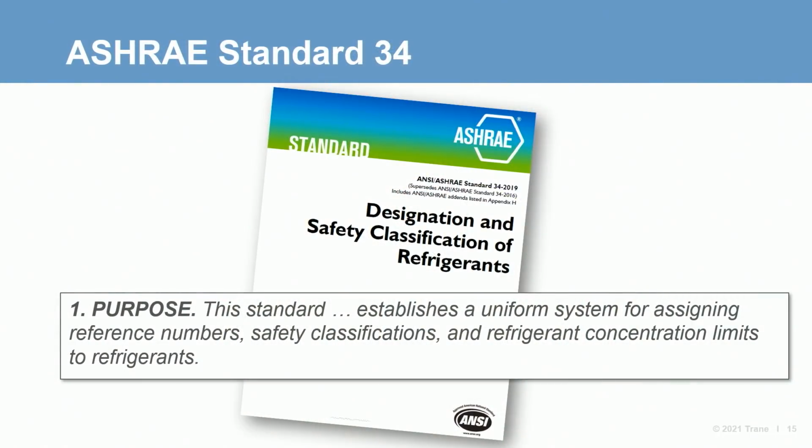First, it establishes a system for assigning reference numbers to refrigerants such as R410A. This helps avoid confusion caused by using brand names such as Freon, or complications of using the full chemical name or formula. Its second purpose is then to define the safety classifications and the refrigerant concentration limits for all types